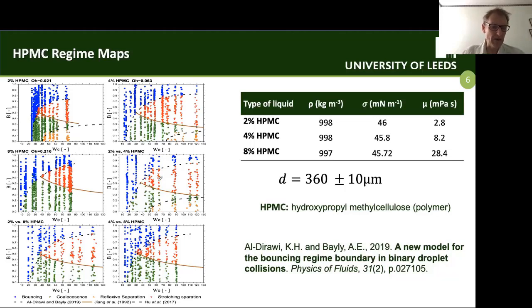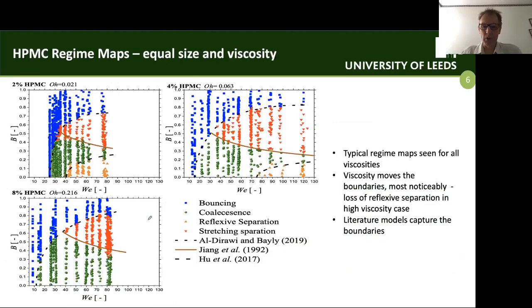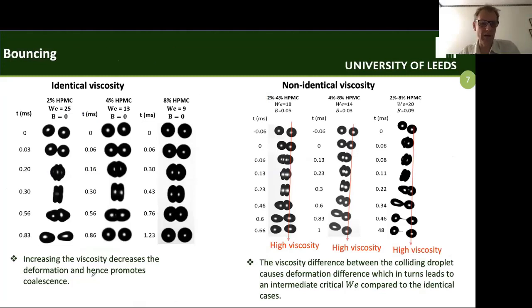And what you'll see, they all look roughly the same. You find this reflexive separation region disappears as you increase the viscosity, and some of these boundaries change. So we've looked at and built models for how some of these boundaries change with viscosity, and looked at improving the models that are out in the literature. When it comes to non-identical viscosities, or viscosity, just first to say then, in bouncing, as you increase the viscosity,